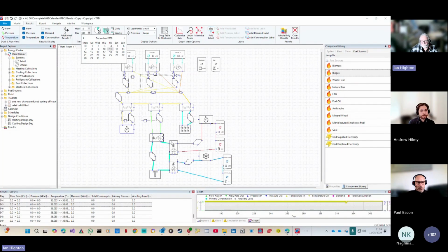So all of that flows around, and obviously you get heat rejection or heat acquisition from the ground loop system, and then this heat pump will try and feed the primary retail loop to keep it at the correct temperature in terms of what you're trying to do. And as I say, you've got the dry air coolers which can cool it, and you've also got the boilers which can heat it, but it's sort of in this sequence.